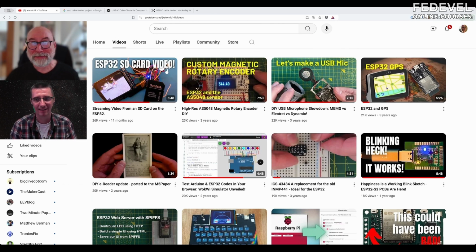The enable signal, and swapping UARTs. I think I blame it on the datasheet not being clear. There was a pull-up resistor on the enable line, and I had a pull-down resistor externally, thinking I'll just pull that down and that will work. But because there was a pull-up resistor, my voltage wasn't enough to actually disable it.